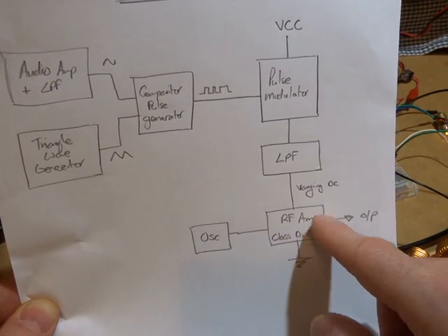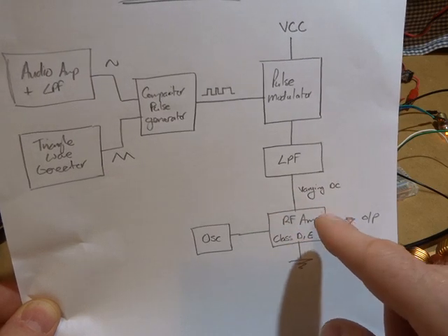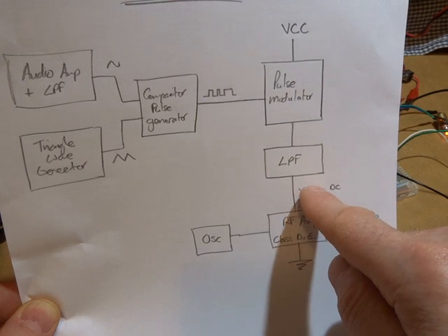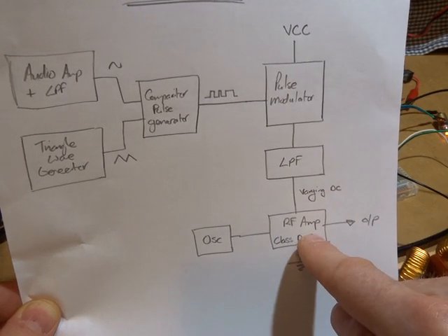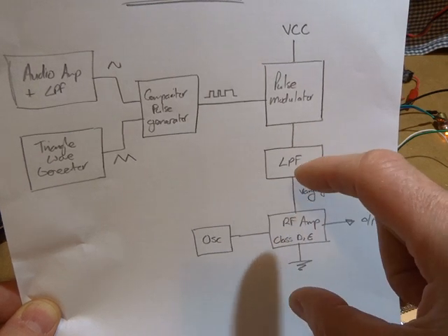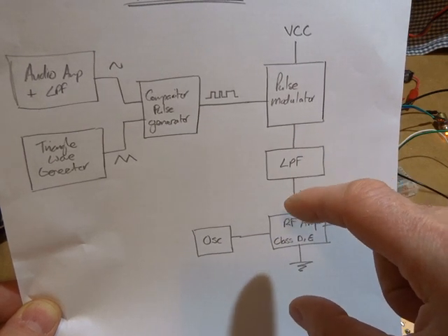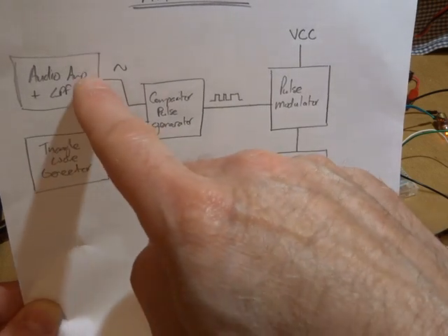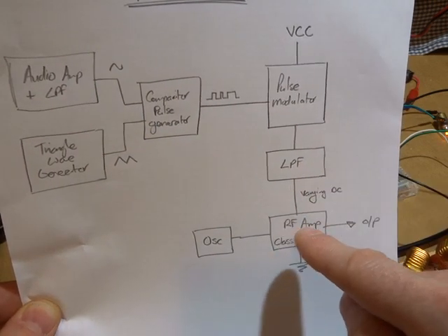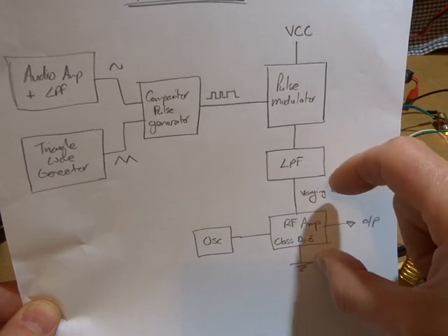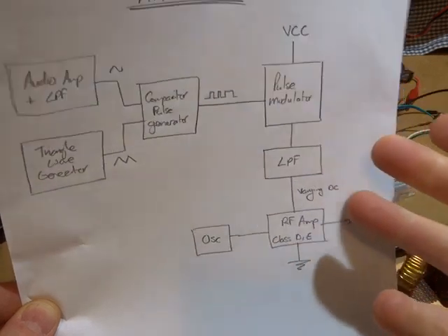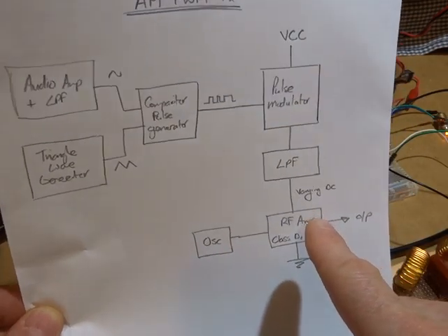So amplitude modulation, as we know, with this particular method, the VCC line that's going to the RF amplifier, that DC there is going to vary, and it's going to vary at the audio rate from our microphone. And by doing that, our output carrier is then going to be amplitude modulated, where we get our AM from.